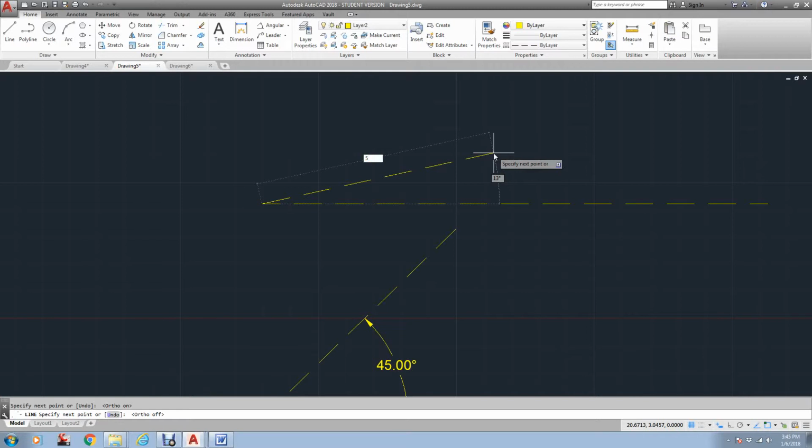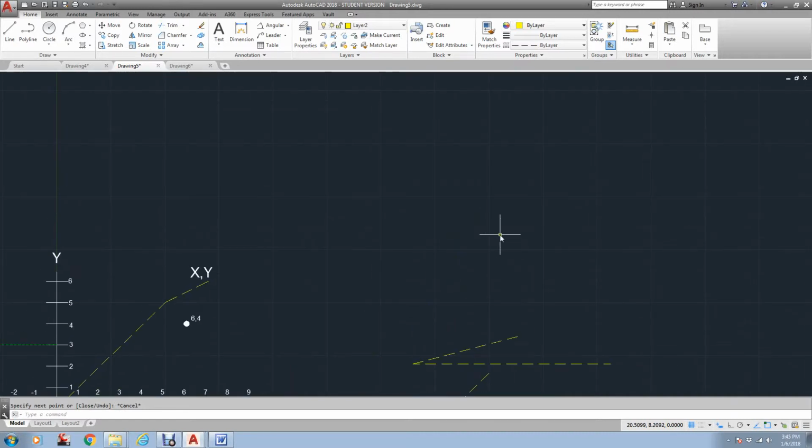That is the key that shares the comma, the less than, but you have to hit shift to get it, and watch what happens. It's going to lock that 5. Now it's asking for an angle, and I'm going to type in 15. So there I've drawn a line that is 5 units long and it's 15 degrees.